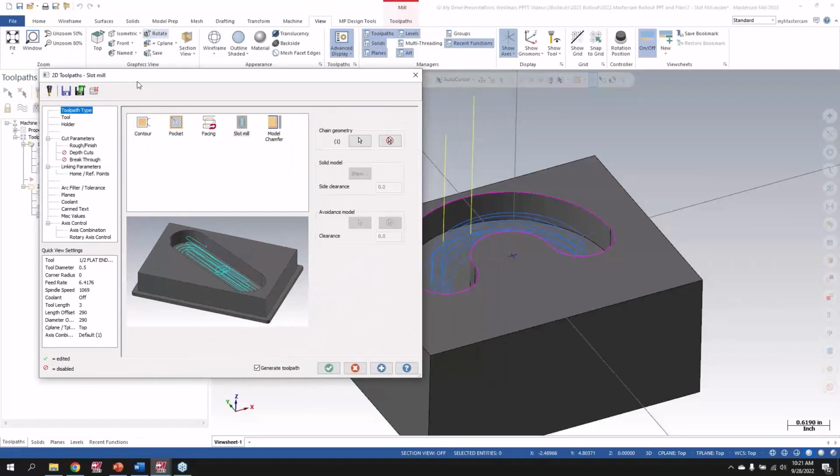When I first loaded 2023, I was always really used to a really handy tool at the very top of the window here, the preview toolpath button that we added, gosh, probably back in X9. So it's been years since that's been added in there. And I was thinking, did they take away preview? I use that all the time as I'm trying to fine tune a toolpath.